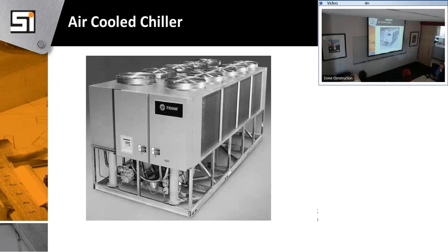So that's how I look at it. Owners now look more global. Now I have a campus, and because of maintenance, when I put all these units on the roof, I get a lot more maintenance. So if I have a campus, I could put a chilled water plant here, and then it's just a bunch of fans on all these roofs. I have to pipe it all over, but I have less maintenance because they're only dealing with a fan, not all the compressors and condensing fans.